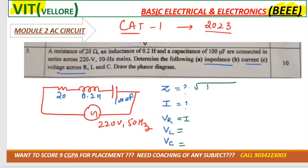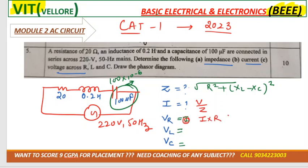So Z is equal to root of R square plus (XL minus XC) whole square. For XC, you need to convert the capacitance, 100 into 10 raised to power minus 6, right? I is equal to how much? I is equal to V over Z, not R. VR is equal to I into R. VL is equal to I into XL. XL you already calculated in Z, right? VC is equal to I into XC, correct?